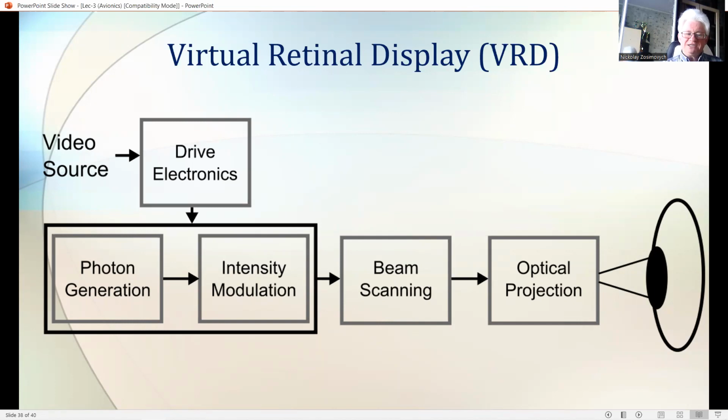The technology offers a number of advantages and is being actively developed by a company called Microvision Incorporated, Seattle in the USA. The current technology of implementing a virtual retinal display involves lasers, optical fibers, and miniature vibrating mirrors for raster scanning the retina of the eye. Together with coupling optics, a binocular VRD thus imposes a significant weight penalty to the helmet.